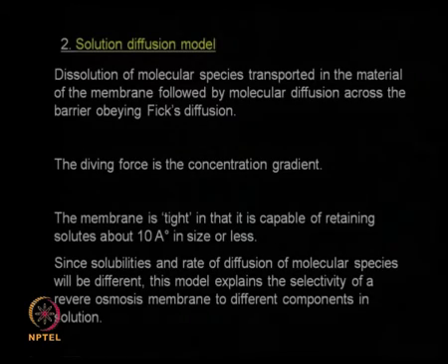Material transport happens because of dissolution of the solute and transportation by diffusion. So the rate of diffusion of these solutes determines the separation efficiency. This type of model is very good for explaining reverse osmosis and even pervaporation, whereas the capillary flow model is very good for ultrafiltration and microfiltration. In real life you may use either the capillary flow model, that is model 1, or the solution diffusion model to understand the separation process.